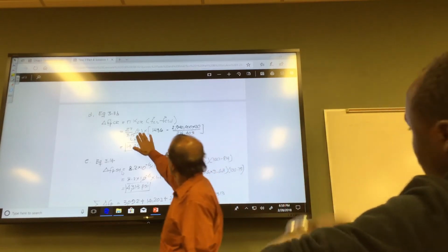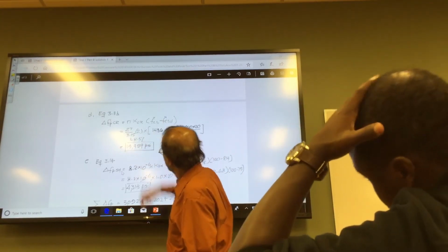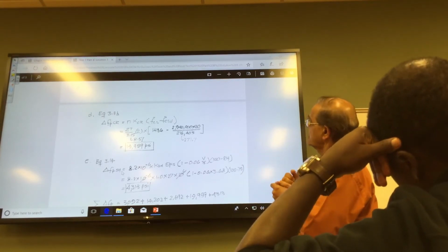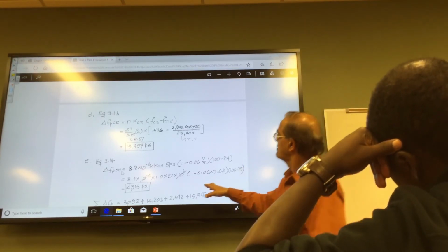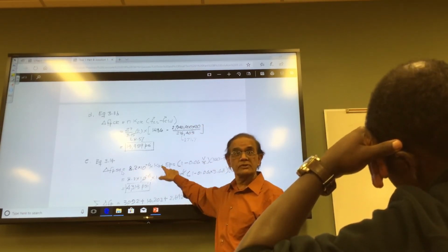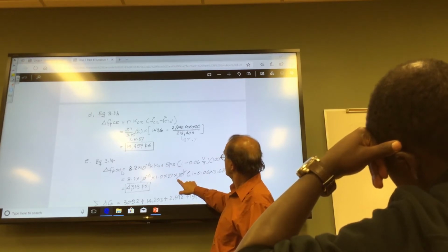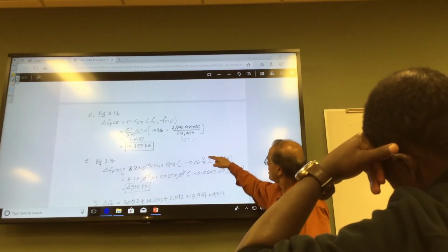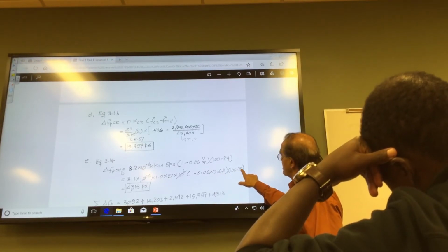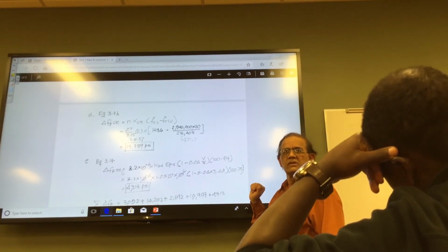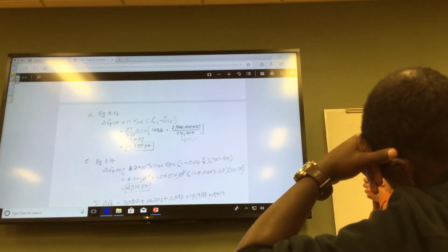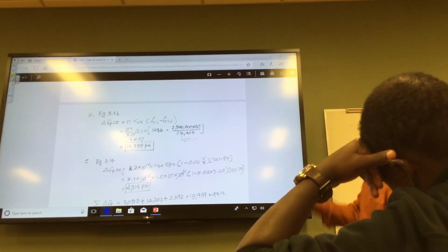And this is the ultimate value. This is for the post-tensioning method, right? And then here is the last one, which is the shrinkage, this is a constant. This is a constant depending on post or pre-tension. EPS is given, and then the volume over surface ratio is given, and then the relative humidity is subtracted, right? So make sure you don't do it the other way around where you just simply put 75. So it is 100 minus 75, so it should come out to be that.